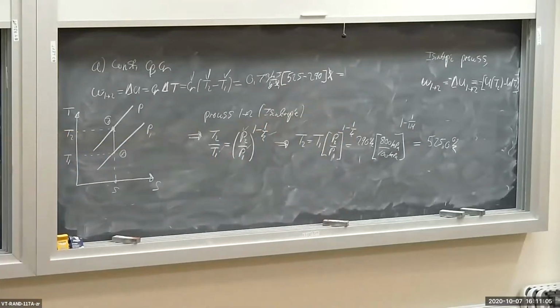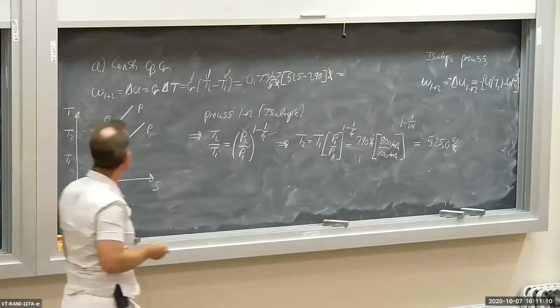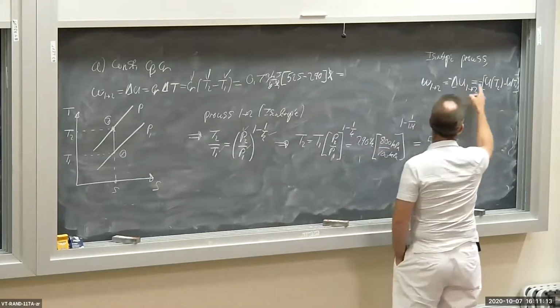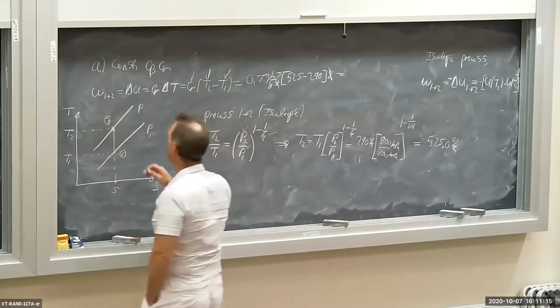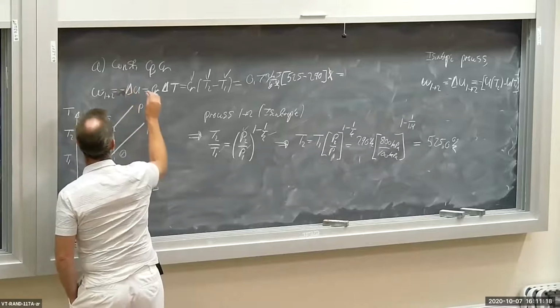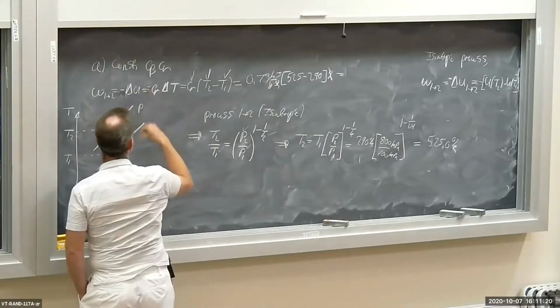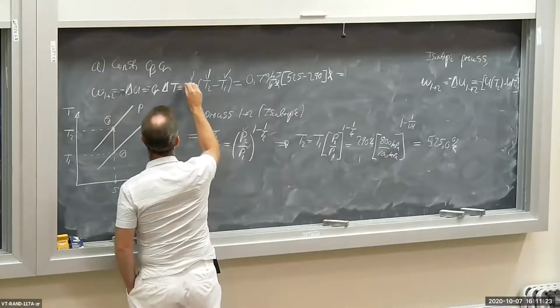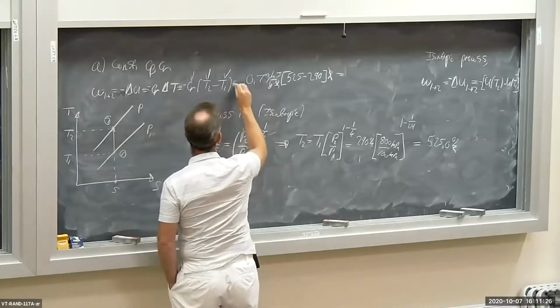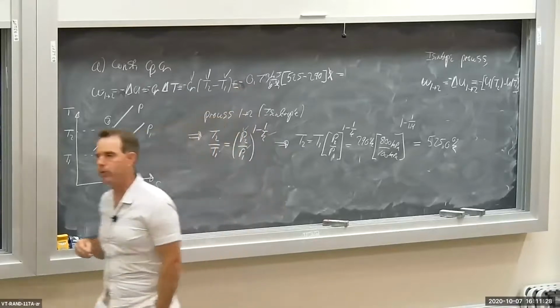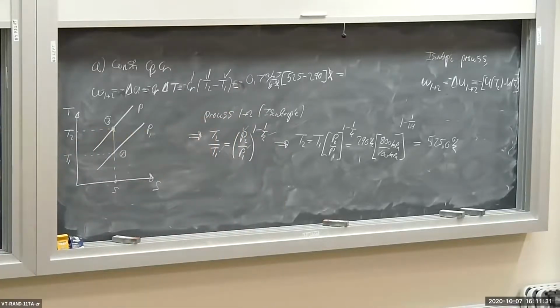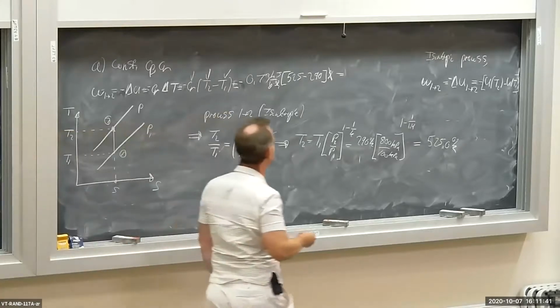And the minimum work then, W1 to 2, actually there's a negative sign. I guess I better keep my negative sign. All that's going to happen is it's going to indicate that work is done on the system, and I'm immediately going to flip the sign to indicate that it is the work on the system. So minus 171 kilojoule per kilogram.